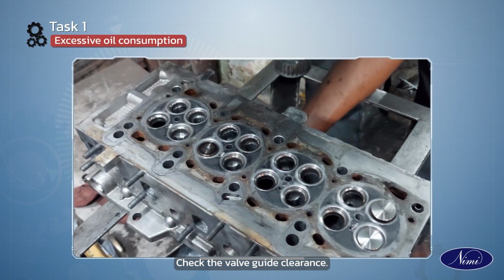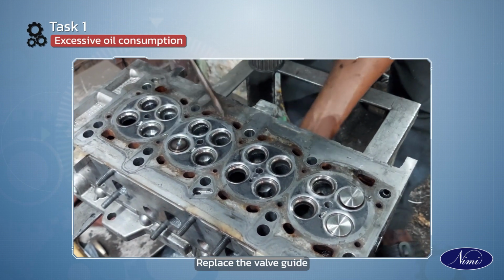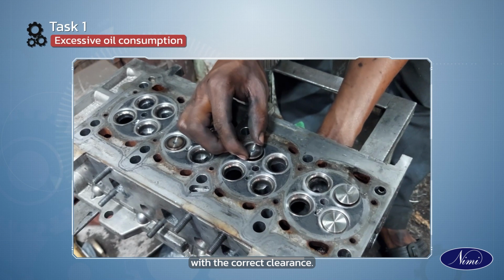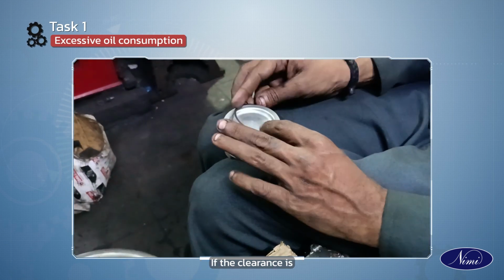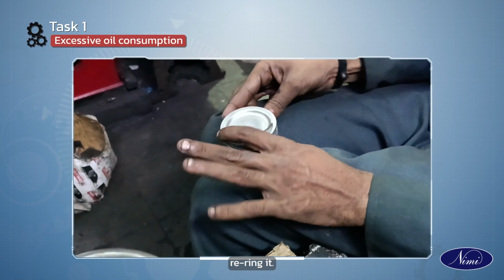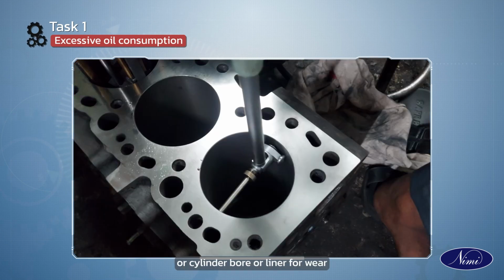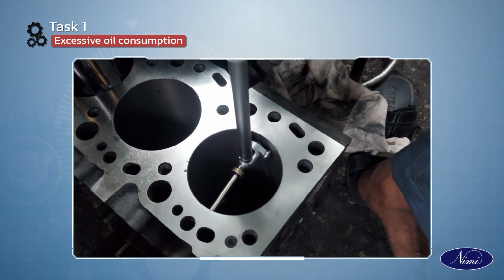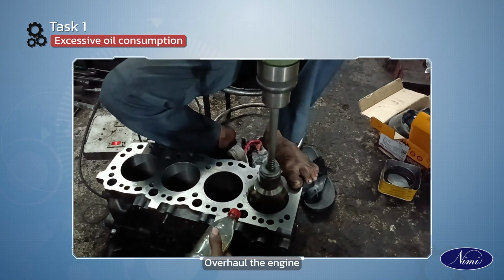Check the valve guide clearance. If the clearance is excessive, replace the valve guide with the correct clearance. Check ring clearance. If the clearance is found to be excessive, re-ring it. Check the piston or cylinder bore or liner for wear. If worn out pistons or cylinder bores are found, overhaul the engine.